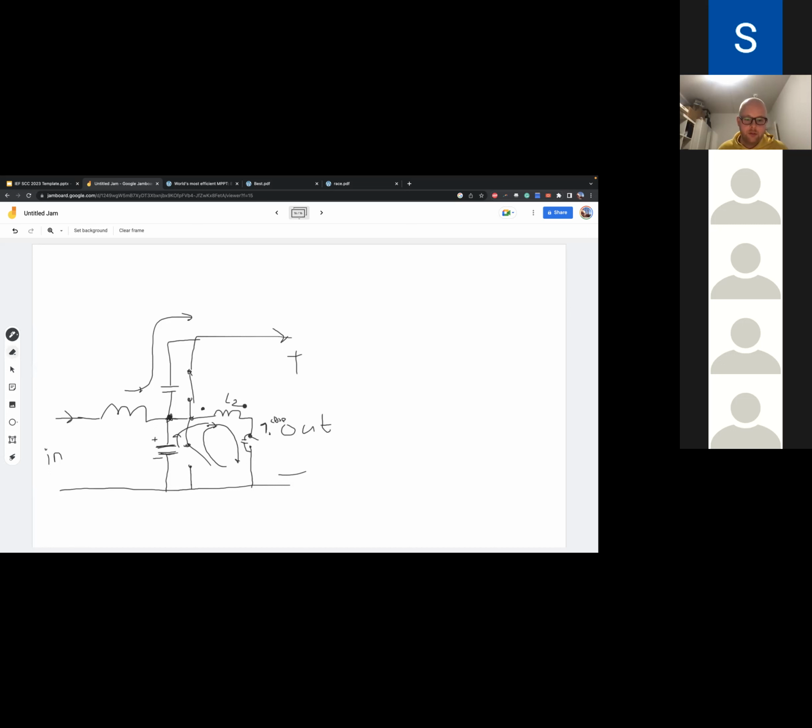And then once that voltage here drops to 0, I close this switch. One sec. First I close switch 1. Then the current here becomes higher than the current through the main inductor, L1. Then I open switch 2. And then the current starts discharging the bottom capacitor and charging the top capacitor. And once this voltage has dropped to 0, I close switch 3. That's the trick I'm doing. It's complicated.